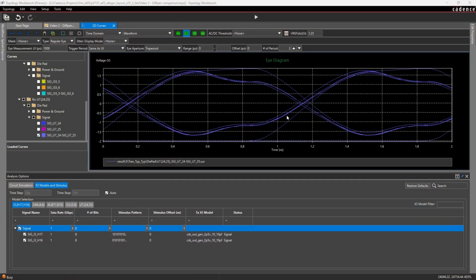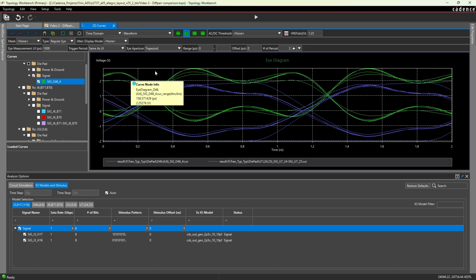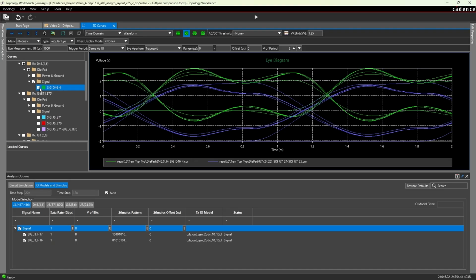And then you have your chips, which need to handle higher frequencies or higher gigabits per second, and those perform better. So we route them differently. So it really just depends on your application. Here, our chip does just fine at the 1 gigahertz range, for this eye diagram and performance. And if we look at the signal, it does its own thing for the RX, the received signal.